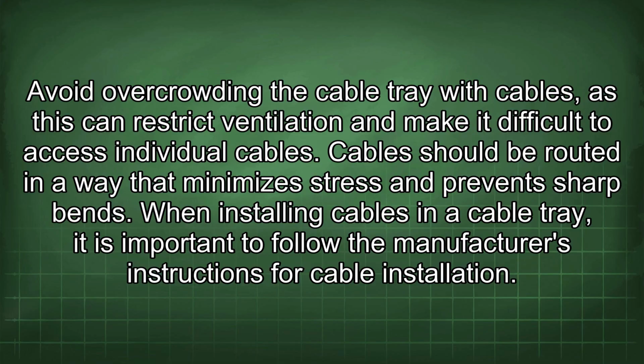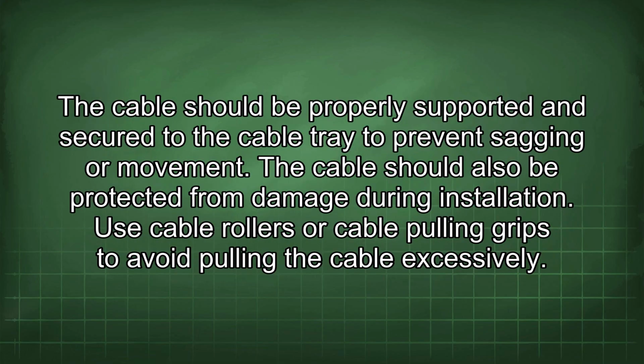When installing cables in a cable tray, it is important to follow the manufacturer's instructions for cable installation. The cables should be properly supported and secured to the cable tray to prevent sagging or movement. The cable should also be protected from damage during installation. Use cable rollers or cable pulling grips to avoid pulling the cable excessively.